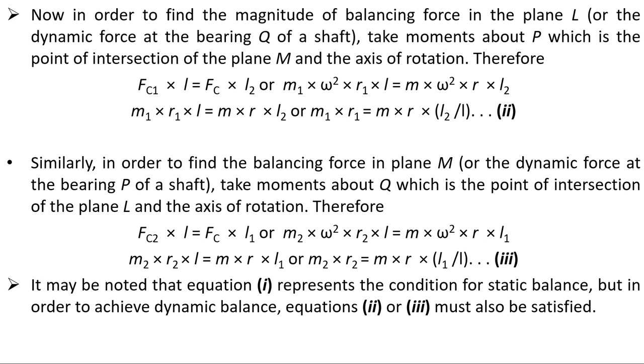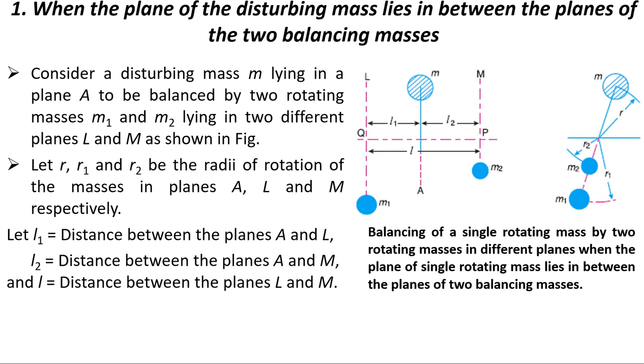Next, similarly, in order to find the balancing force in plane M, that is the dynamic force at the bearing P of the shaft, you have to take the moments about Q, which is the point of intersection of the plane L and the axis of rotation.